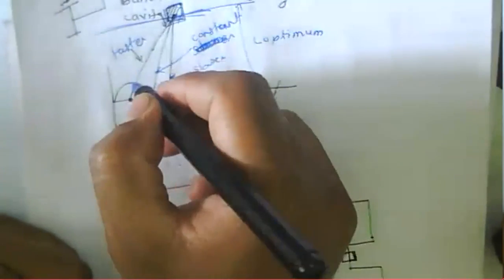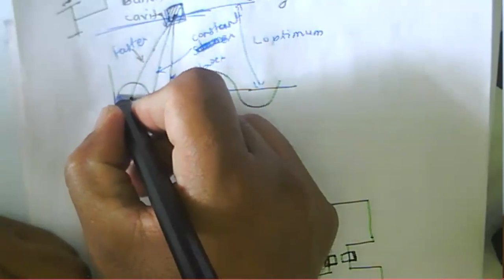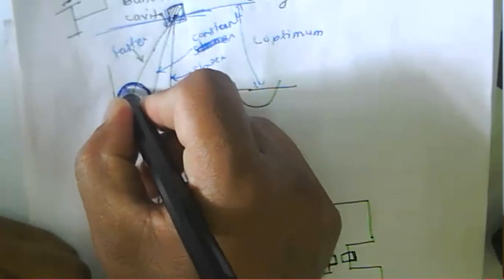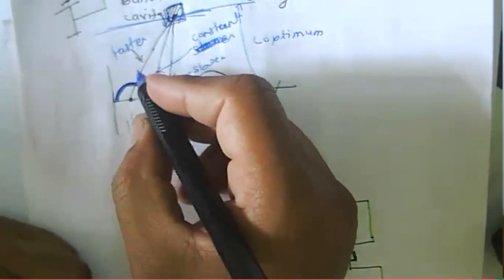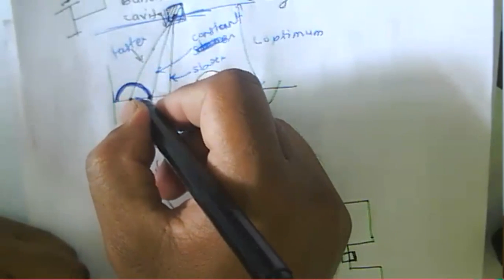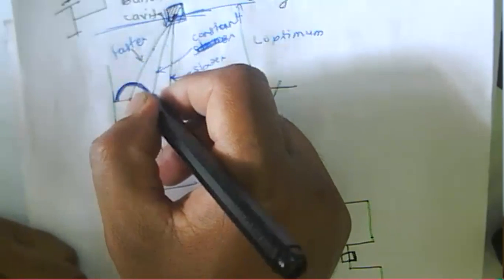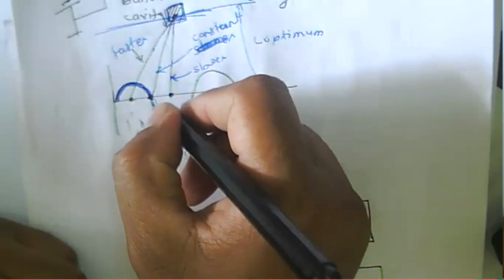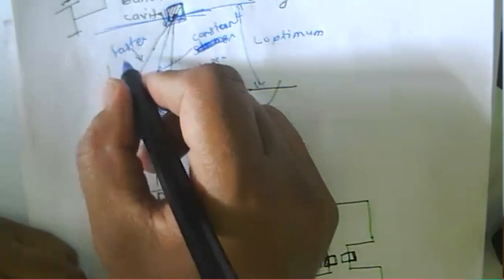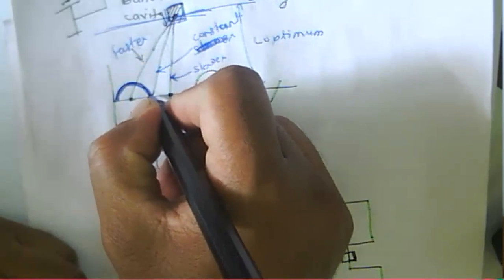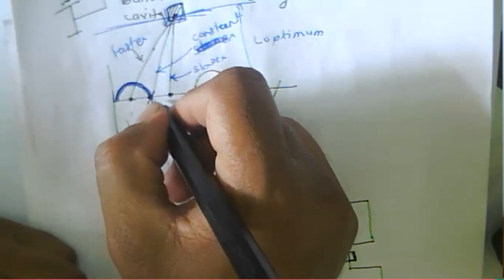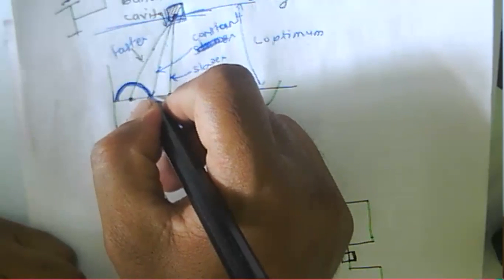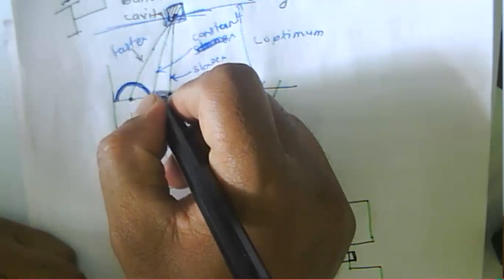The velocity of the electron increases because they are moving in the positive half of the RF cycle. Okay, this one is about your RF input. When an electron moves in a positive RF cycle, it will be faster, meaning velocity increases. An electron moving in a negative half cycle lowers its speed. Velocity will be lower as compared to this electron. And those that are moving here, where we are changing from the positive to the negative half at this particular place, will have a zero field. Means we can say that the electron will be of constant velocity.